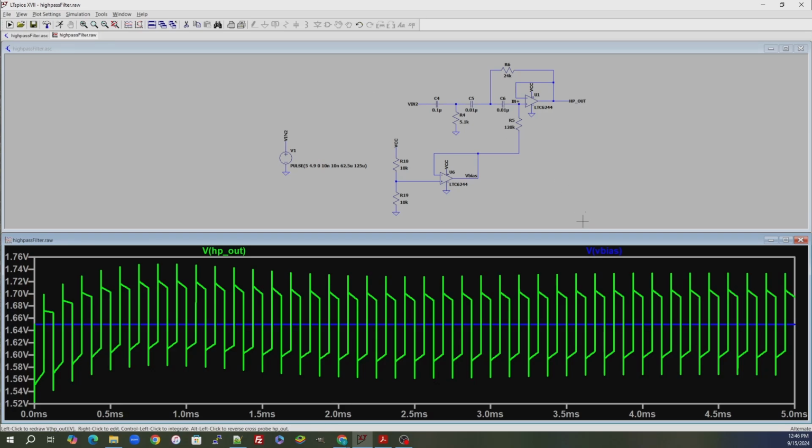So the other thing that we want to do is, because it is a small signal and our ADC on the microcontroller may not be that accurate, we want to actually put some gain on this so we can see a little bit more of the voltage range on this thing. So we want to put a gain amplifier on the output of this and multiply it by, let's say, 2. We can choose anything, but for this example, we will say we want to put a gain of 2 on it on the output.